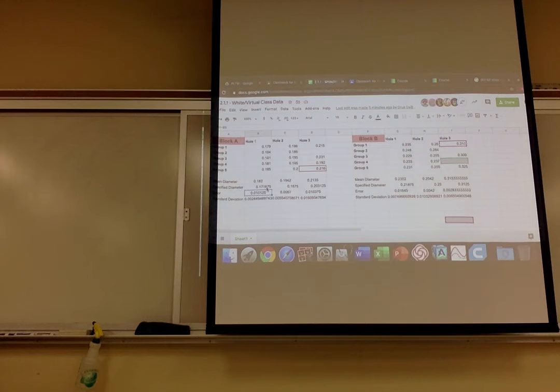Oh, you want section view? Section view is right here. And you're going to place some line symmetry. This one's real good. Cut it right down here. I'm going to place the section view over here. It's basically going to cut, and either these arrows are where you're going to look. So it's either going to look this side, or it's going to look on that side.